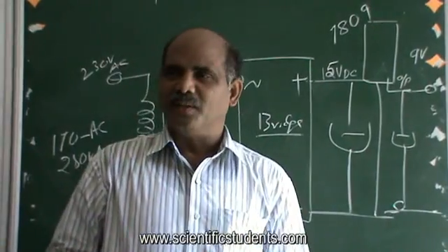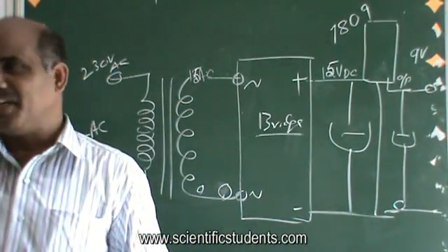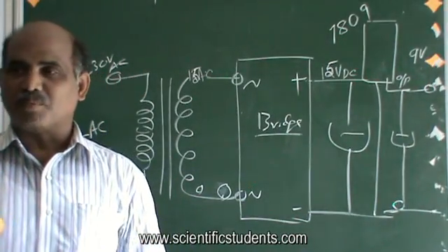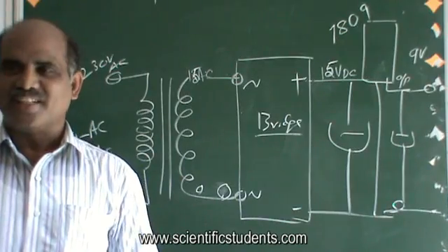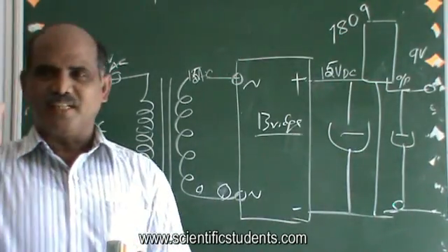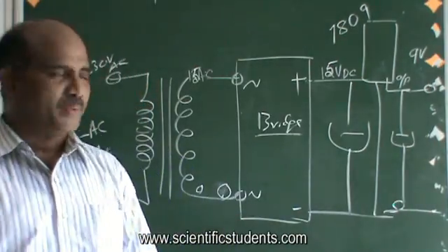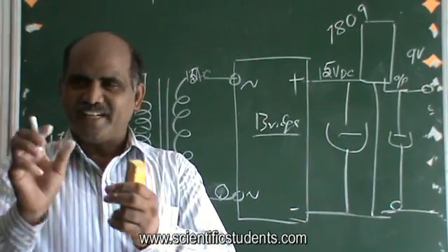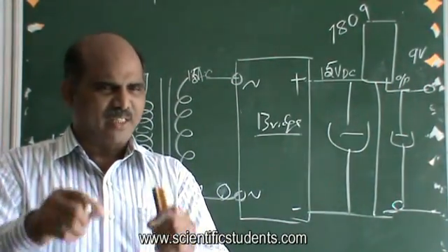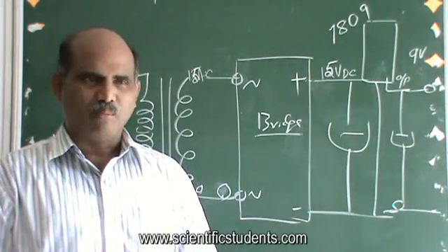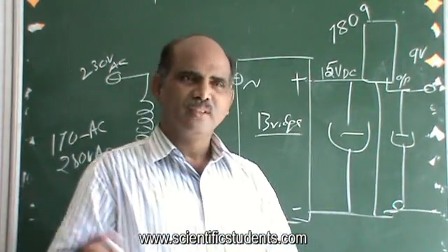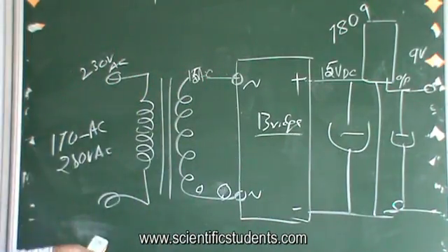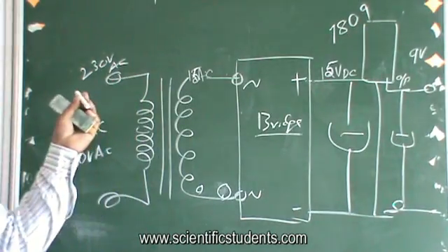Okay, my dear friends, yes or no? All your projects will work nicely if you build this regulated power supply for constant 9 volts DC. You build a project and use that plus and minus output for all your projects. Instead of the 9 volt battery connection socket, you just solder another 2 wires in parallel, with the same connections on the board, and connect to this. They will work, yes or no? Happily they will work without the botheration of any voltage variation on the input side.